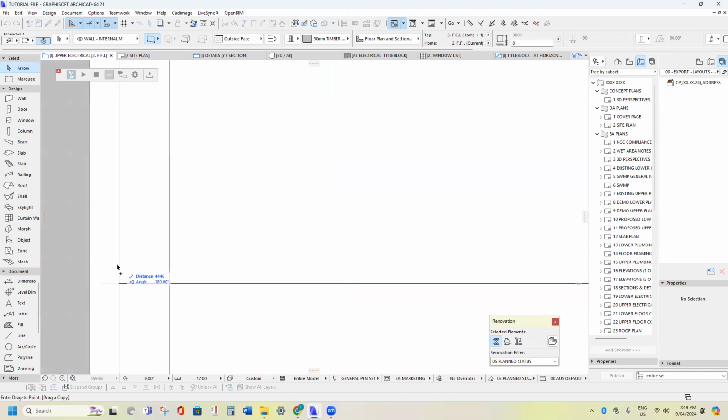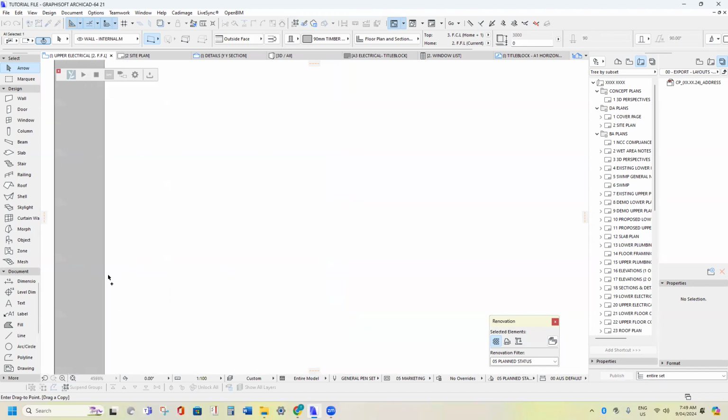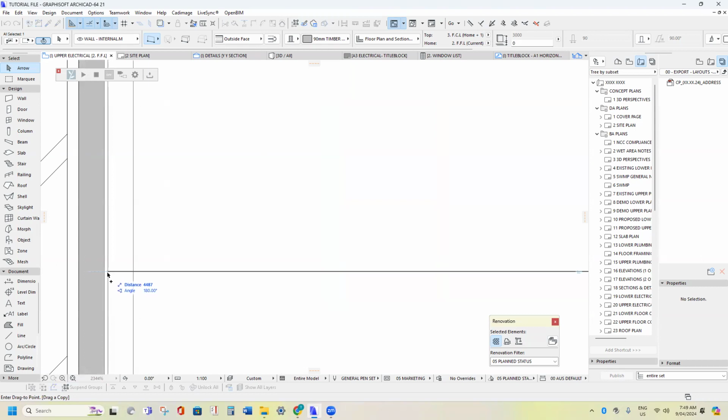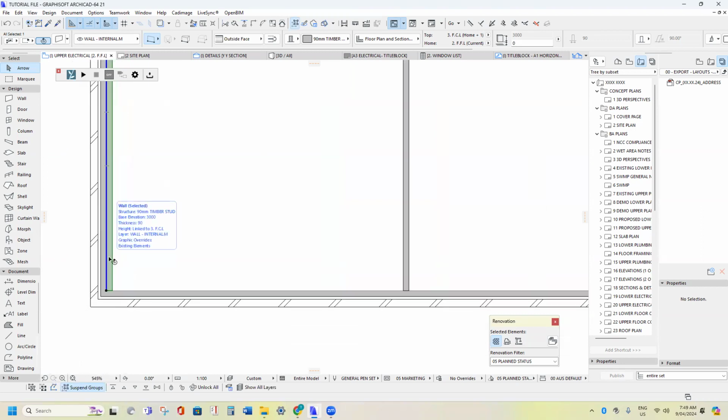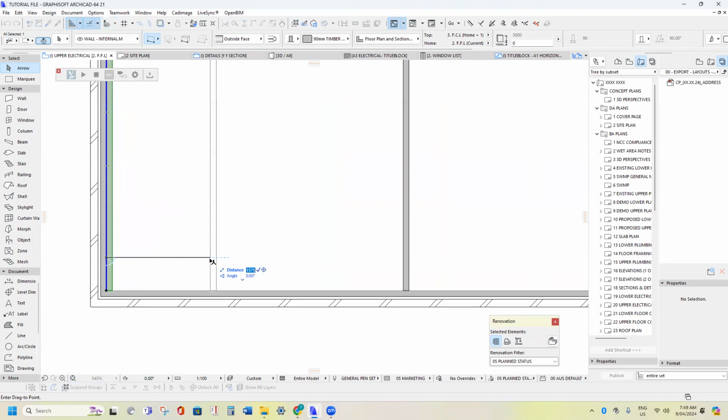If you've got a mouse with a ball in the middle, you can zoom in and zoom out. So zoom in if you need to, and see where that's got a right angle symbol showing. That means it's right against it. So then click, then you know that's accurate, and then you're going to press Control D, bring it back and press R, 3600 as well.